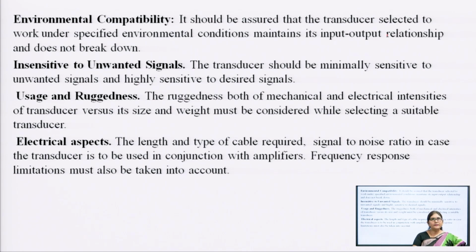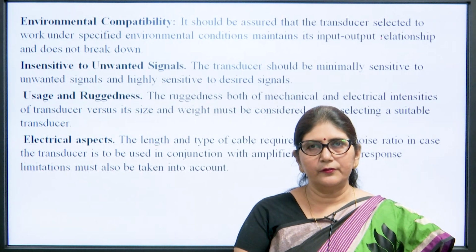Then insensitive to unwanted signal: the transducer should be minimally sensitive to the unwanted signal and highly sensitive to the desired signal. Then usage and ruggedness: the mechanical and electrical ruggedness of the transducer versus size and weight must be considered while selecting the transducer.